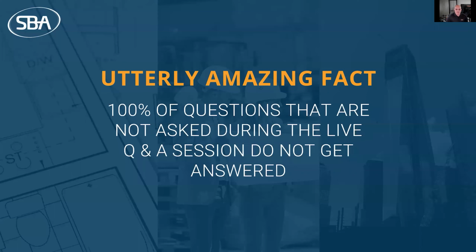So I do see someone has a question about wire size and type for MSTP. Follow the 485 standard and you'll be good to go. RS 485, anywhere between 20 to 24 gauge, typically 3-wire. Surprisingly, RS 485 does not require shielded wire, but I would recommend shielded wire. Can you mix wire types? I don't recommend it, especially conductor types, because you can have different levels of impedance.